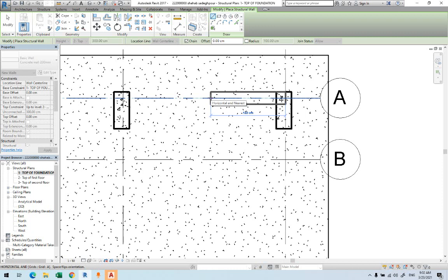Now you remember we said the grid lines, architecture, place it in a way to be the center of the wall, yes? So I can draw it over the center line because I know the walls will be on the center line. Well, what if I have a case where, for example, I want my finish face exterior? So if I click here, what will happen? Realize that it will go outside of that, so that it will give it somewhere else.